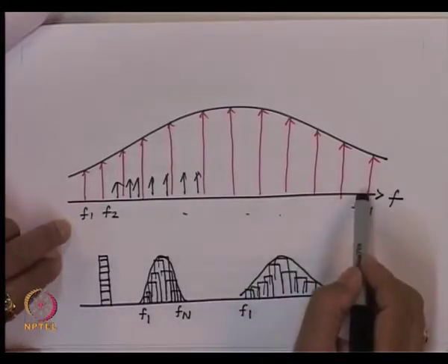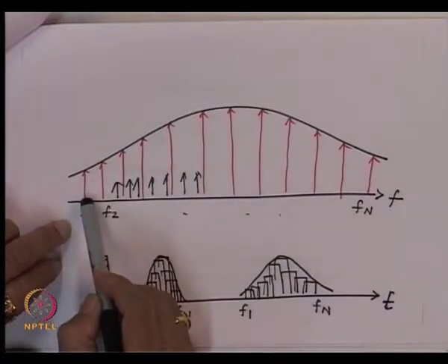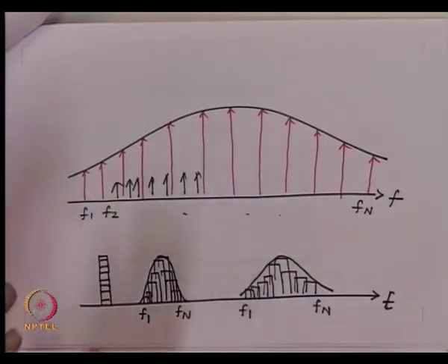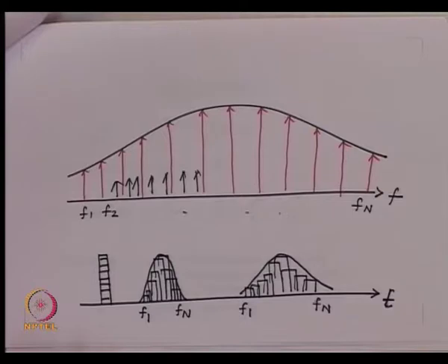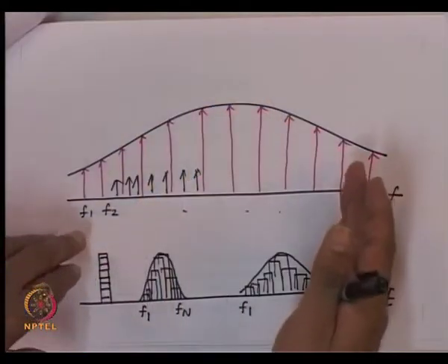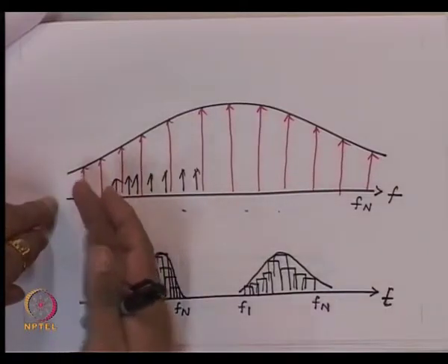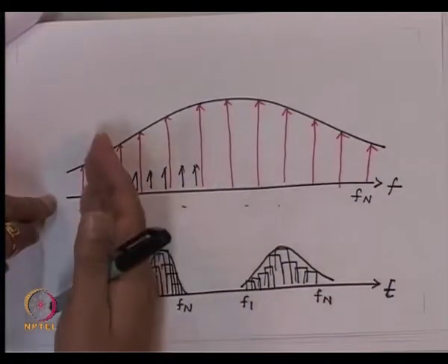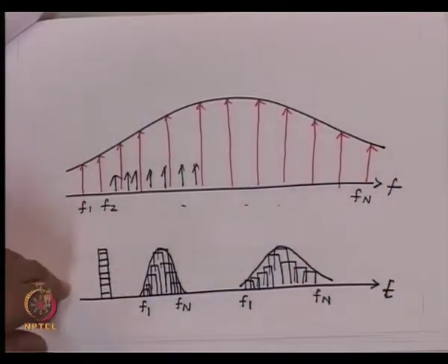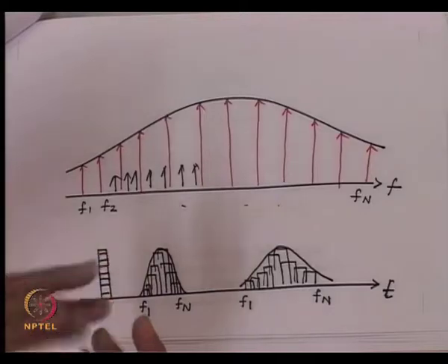Now whether these frequencies travel faster or these frequencies travel faster, the dispersion is because of the spreading of the pulse because of differential velocity between different frequencies. So if the pulse has to remain intact, all the frequencies must travel with the same speed. In one case, these frequencies travel faster, so these frequencies go ahead, these are left behind. In the opposite sign for dispersion, these frequencies travel faster, these frequencies are left behind. In either of the case, there is going to be a pulse broadening. There is no shrinking of the pulse.